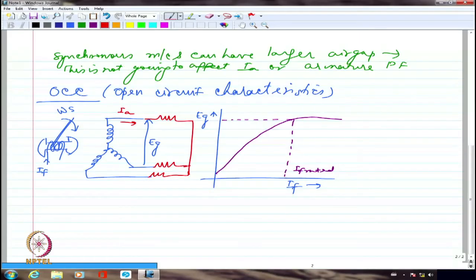The rotor is revolving physically, and that is at synchronous speed. So that is definitely going to create a magnetic field which is revolving in nature. The other one is due to the three-phase currents that are passing through the three-phase winding of the armature, which is also revolving in nature. Now both these things are going to definitely induce EMF in the stator winding itself. Please remember, the stator winding is stationary.